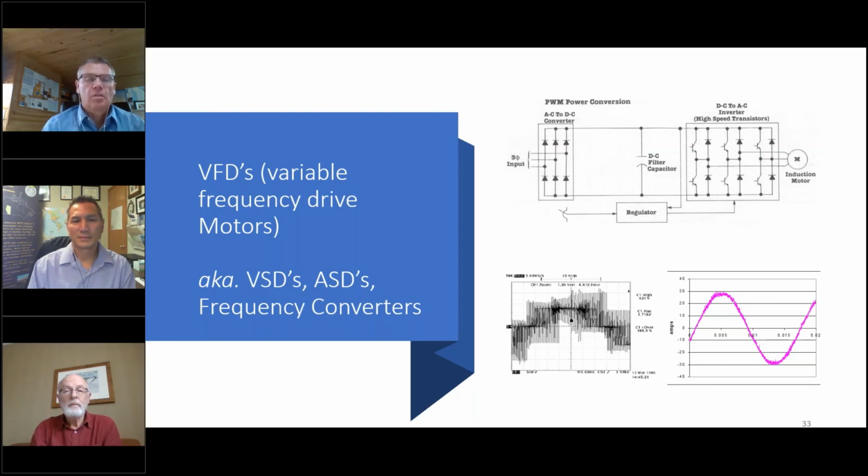So there's what we call a withstand voltage on the insulation system. These little peaks accumulate, and they have a high voltage impulse. So the VFD capable motor has an insulation system to withstand a certain value of those dV/dts. If they exceed that, then you have to have additional filtering.